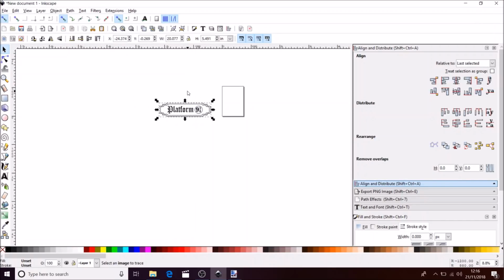All right, now with Inkscape you can't print it all in one go, unfortunately. If you see this page shape, that's an A4 sheet, or you can change the dimensions if you want. I have it at A4, and we need to put this onto there, and only what's in that will print. So first thing I need to do is reverse this sign shape. Now, if we print it out like that and then put it onto our board, the way I transfer is using the LaserJet lacquer thinner method, the sign would come out backwards. If you just want to carve straight through the paper, print it out just like that.